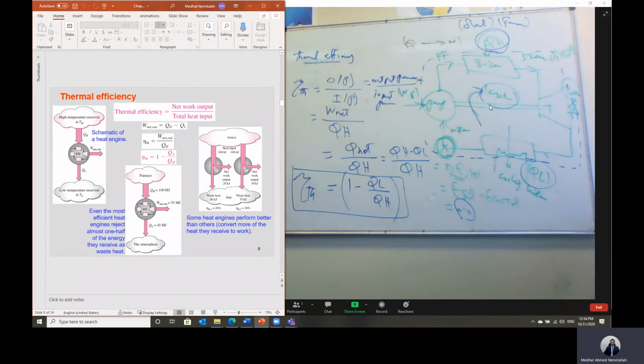But this is the concept of operation of a cycle, like what we said. This pump cannot handle a saturated mixture of liquid plus vapor under high temperature. It can handle only liquid water. And for this system to work on a cycle, we have to get back to the same initial point, which was liquid water. So we have to reject this heat so that we can retain the same initial point. Then this pump can handle this water, and then we can repeat this cycle. Then we can generate continuous work out of this system.